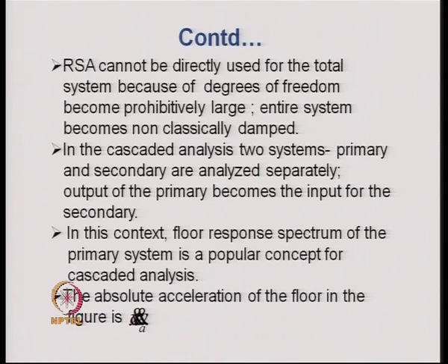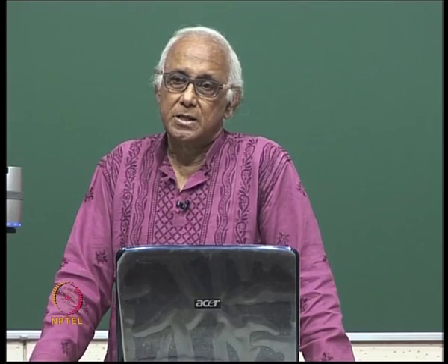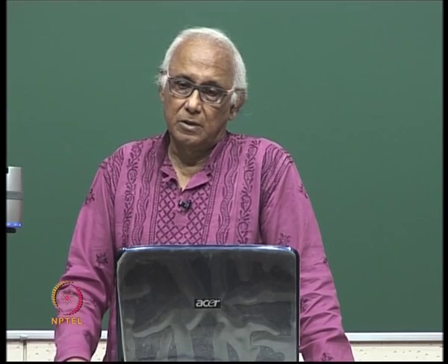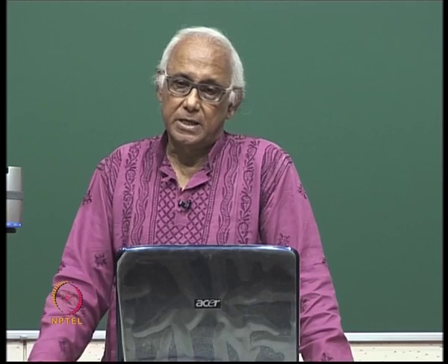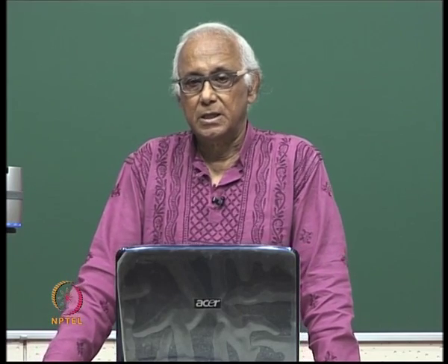These secondary systems are considered in a different way, in the sense that they are not clubbed along with the primary system and the total system analyzed for the earthquake excitation, because in that case the number of degrees of freedom involved becomes too many.